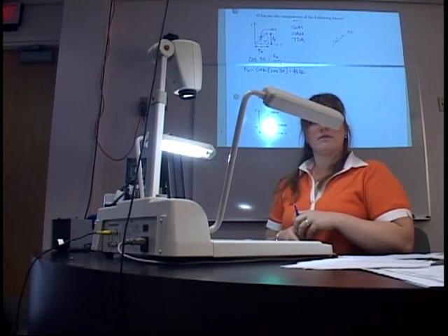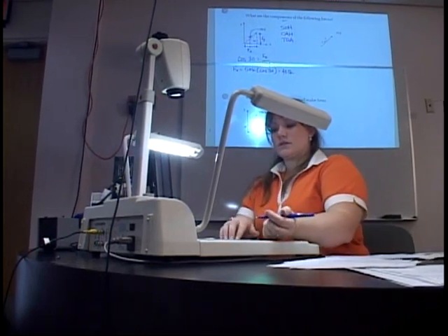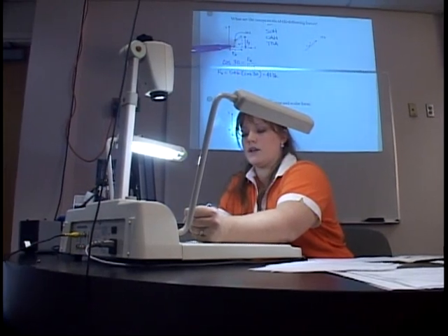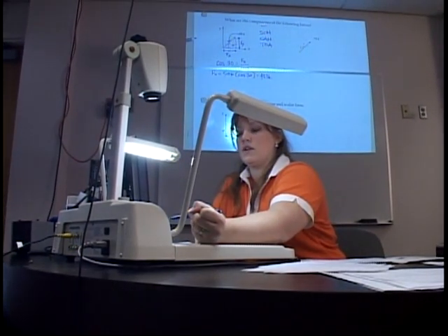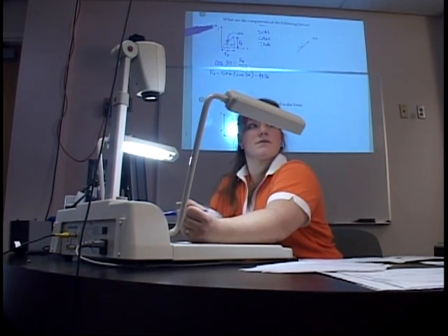Make sense? And if you want to find Fy, now we're talking about the leg opposite of the angle. So we're going to use sine, which gives 50 kips times sine of 30, or 25 kips.